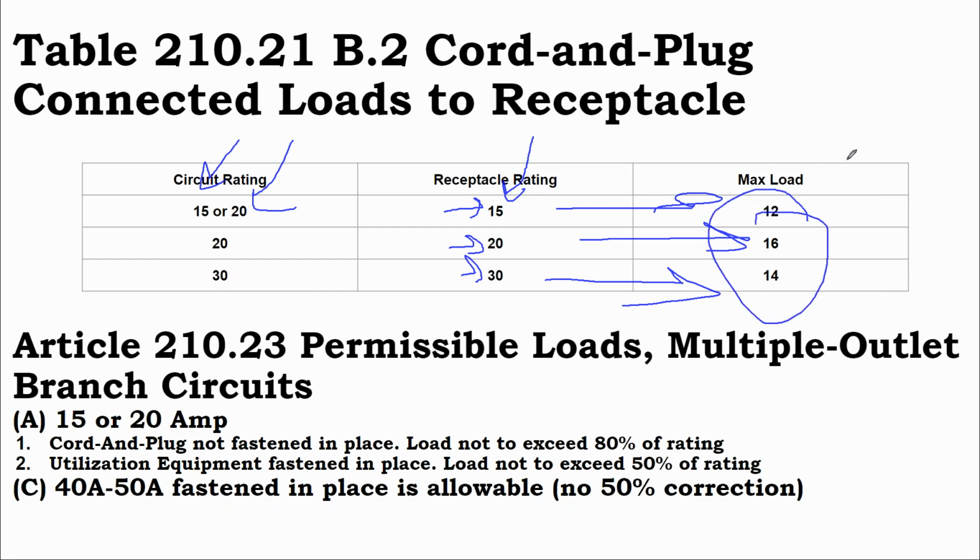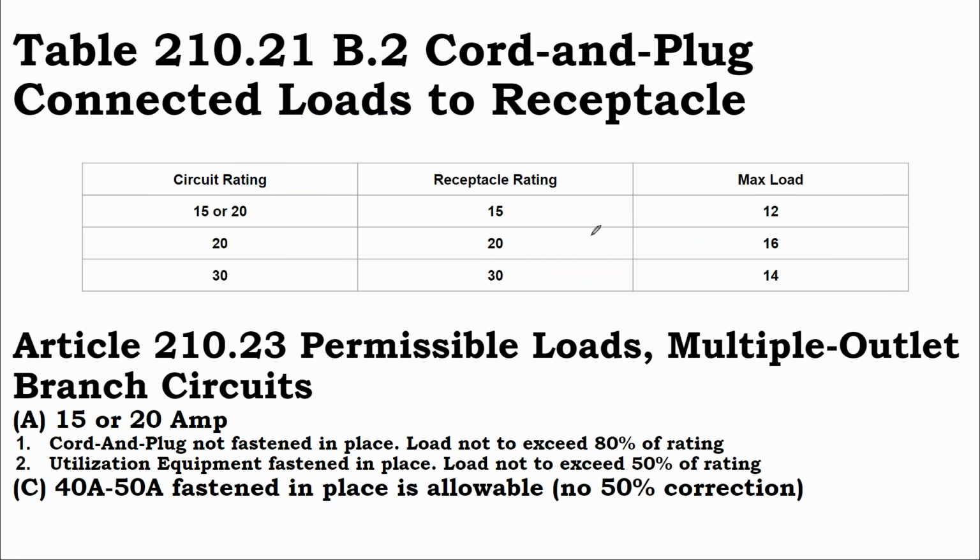If I put a 15 amp load into a 15 amp receptacle that's on a 15 amp circuit, it would trip immediately, and it might trip on the breaker side of it too, depending on where in that 25% extra headroom the real amperage of the device lay.